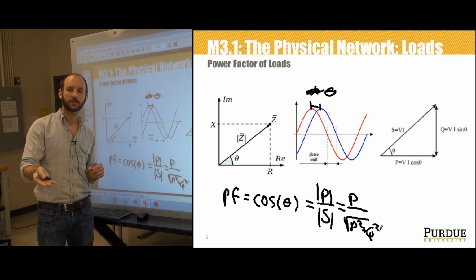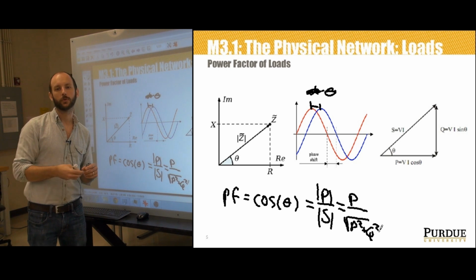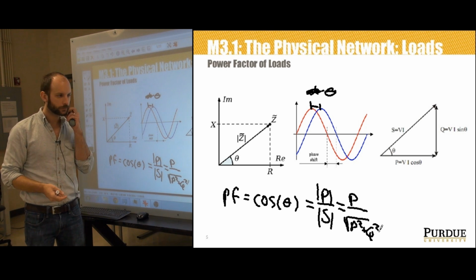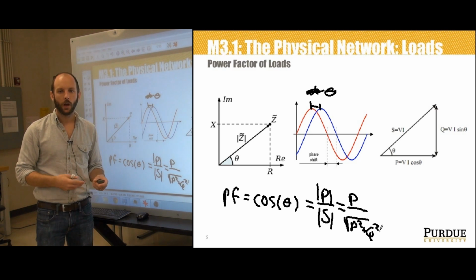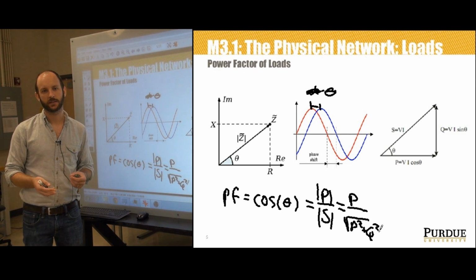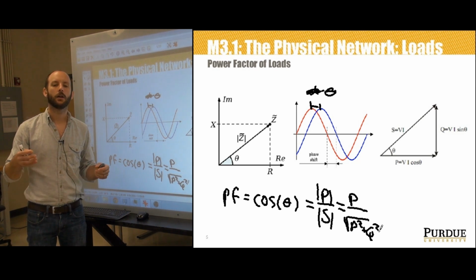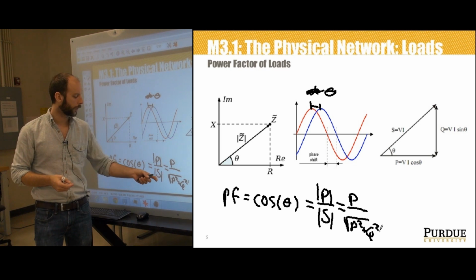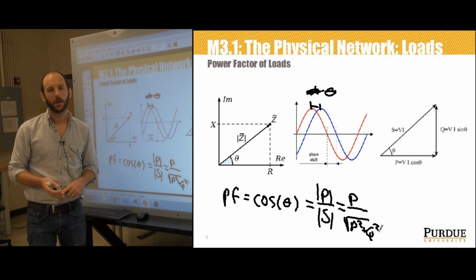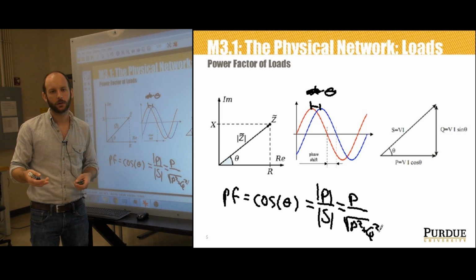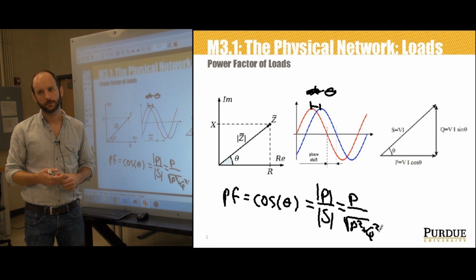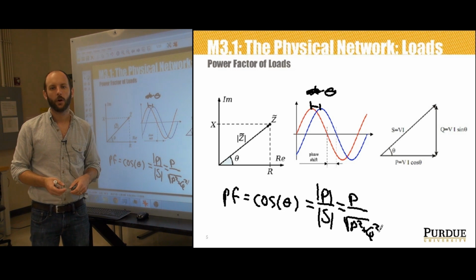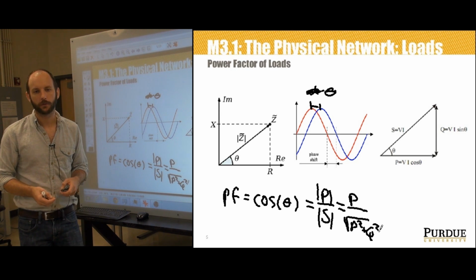And there are resistive portions in the circuit that will produce Joule heating, and therefore energy loss. So owing to this property of occupying lines with excess current and requiring higher equipment ratings per kVA, reactive power is jokingly, maybe not jokingly, referred to as the cholesterol of the power system.